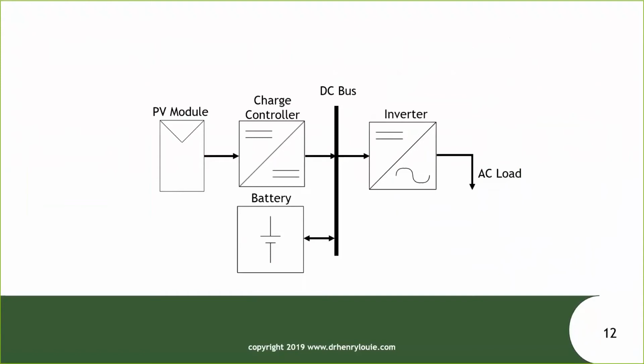And inverters typically will also have a protective feature called a low voltage disconnect. What that does is it disconnects the load if it senses a battery voltage dropping below a set value. And this is really important if we want to maximize the lifespan of our battery. We don't want to deeply discharge batteries, especially lead acid batteries, because they'll fail a lot sooner.